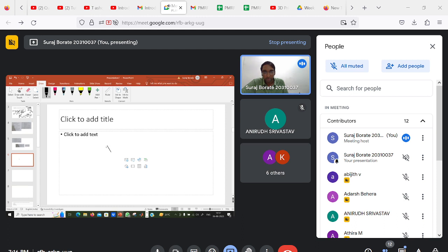If I have two free floating frames, how many parameters do I need to define the relative pose between the frames? When we say pose, it means position plus orientation, both. So what is the relative orientation and relative position between the frames? How many parameters do I need?